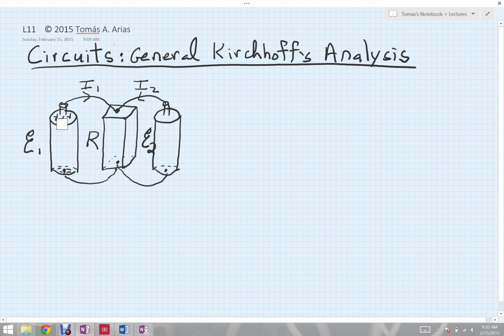That's how we know that the batteries maintain this magical constant potential difference from their bottom to their top. However, if we then take such a battery, a real battery, and wire it into a circuit like this, where now current begins to come off of the top of the battery, things begin to change. That chemical reaction can only occur at a certain rate. And if these currents get large, we'll be removing positive charges so quickly off the top of the battery, we won't be able to replace them sufficiently quickly. There will be a drop in the total charge on the top plate of the battery and a corresponding drop in the potential of the battery when there is a large current.